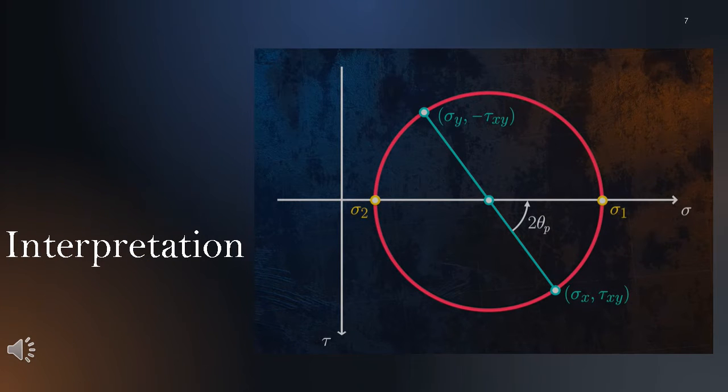Mohr's circle is traced on a stress plane. In said stress plane, the y-axis represents shear stress, while the x-axis represents normal stress. It is worth noting that positive shear stresses will be depicted below the zero mark on the y-axis.